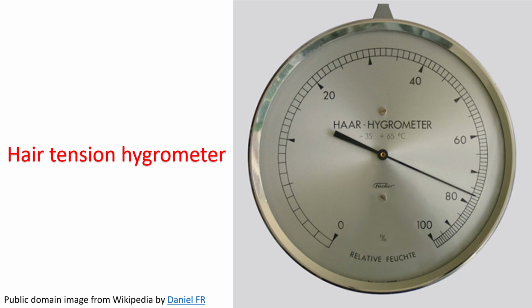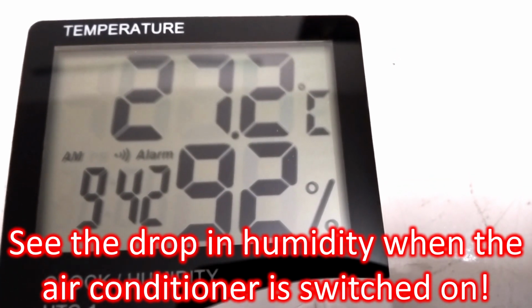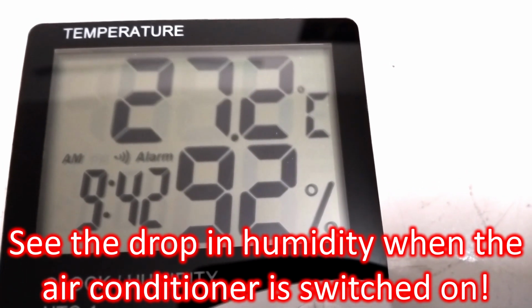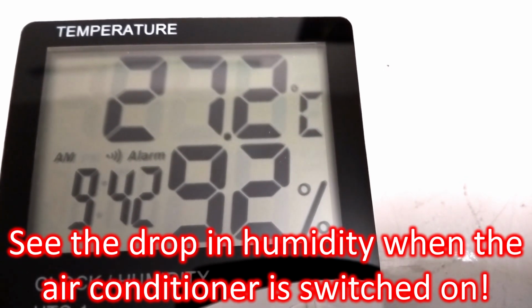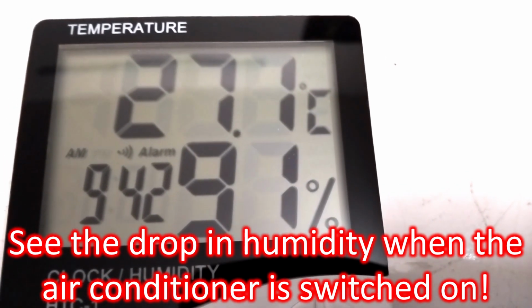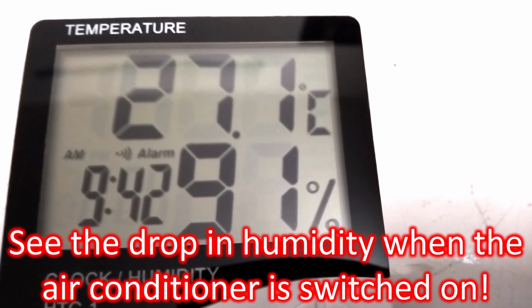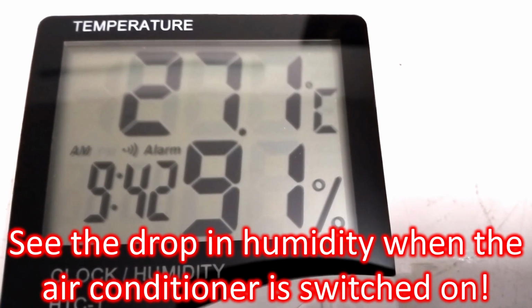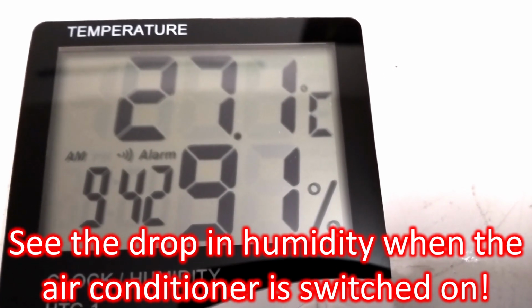Historically, there were many other methods of measuring humidity as well. Electronic devices can measure the temperature of condensation or dew point to assess humidity. Alternatively, they can sense changes in electrical capacitance or resistance with changes in humidity. Capacitive hygrometers measure the effect of humidity on the dielectric constant of a polymer or metal oxide.